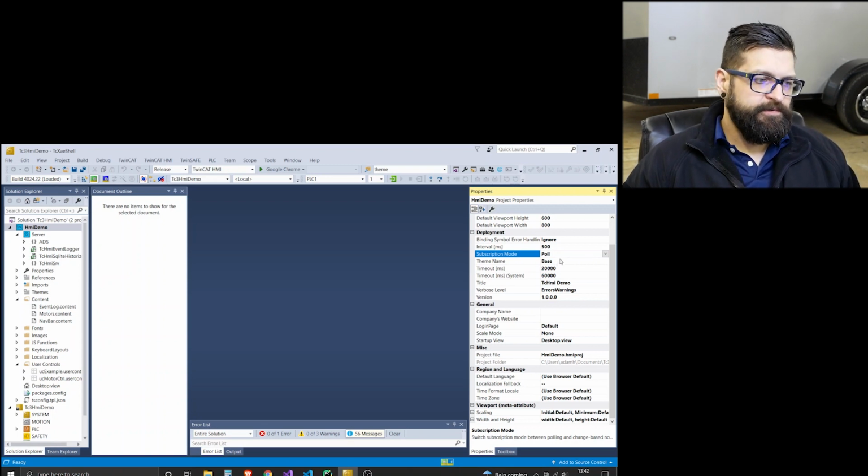So it's just something to think about when you have a lot of analog values and you're using a subscription method of on change, that you could be generating a lot of HMI refreshes of those symbol values that aren't really needed. And then again, this is going to be based on the hardware that you're running. What's the communication overhead? How much system resources are available to communicate back with the PLC? How many total symbols are you bringing over? So that's really going to be based on your specific implementation.